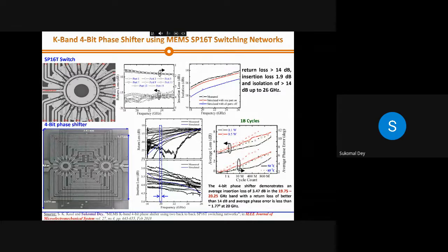Throughout these operations, keep the power level on the lower side. When you are completely satisfied with the temperature of 85 degrees Celsius, then you can be a little bit greedy. You can increase the power level from 0.1 to 0.2 to 0.3 like that. In most cases, the industry wants up to 1 watt of power for these kinds of devices, so minimum one watt of power.